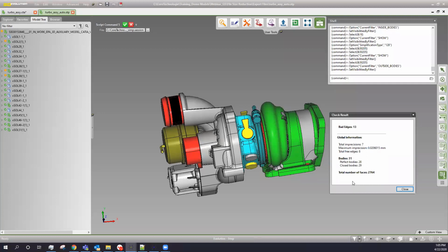What we like to do is simplify it, then convert it, because you take out steps. When you're trying to optimize the process for automation of geometry simplification, you don't want it to include a bunch of extra steps that are just going to increase the time it takes to process. We do have the ability to heal and stitch certain models and make them a solid model. Sometimes when you need a 100% solid model, you'll have some imprecisions in the model. If you do a heal and stitch initially, then you're adding a process and trying to heal and stitch faces that are essentially going to be filled in down the road. So you're actually adding a lot of processing time.